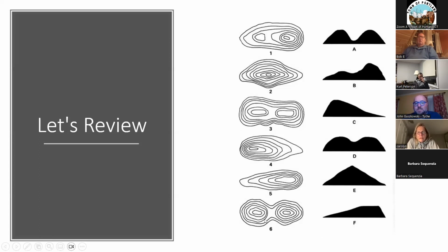Yeah. So if you look at 6, we have a number of contours that are relatively close together and stack up. That would indicate a steeper slope. Right. So that represents A. Okay. D, on the other hand, we have fewer lines of contour, which means less difference between the low point and the high point, and less difference. So it's a gradual downhill back to the uphill. Less difference in between the two mounds. So that's A and D. What do we think about B?